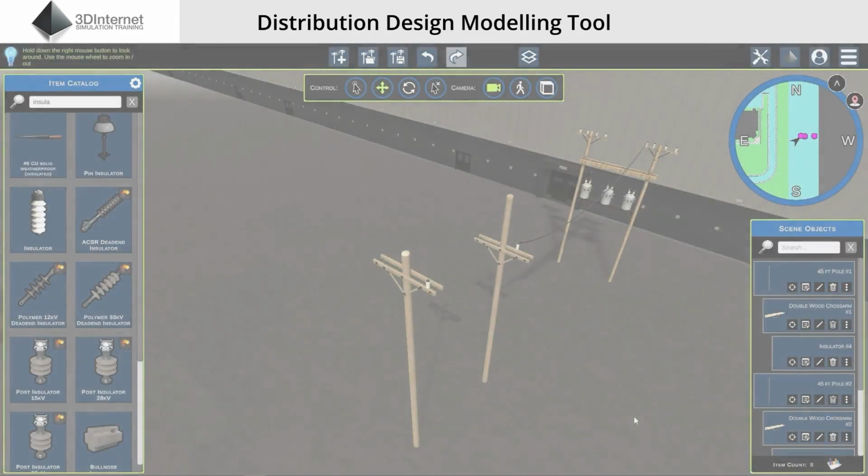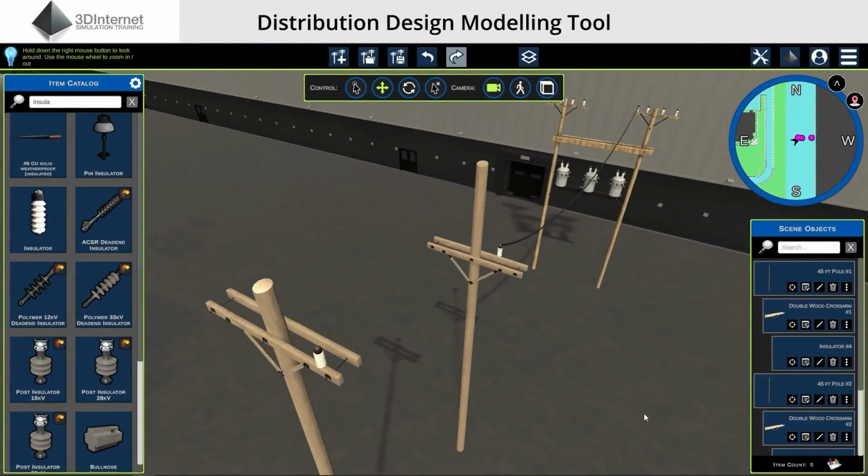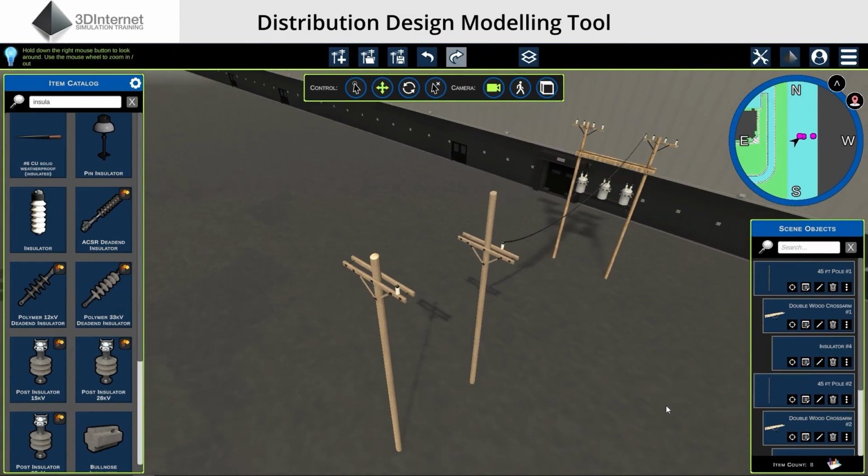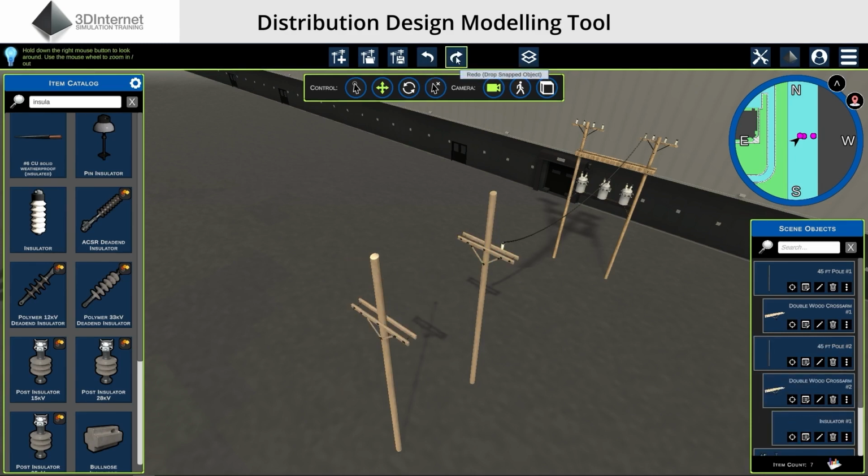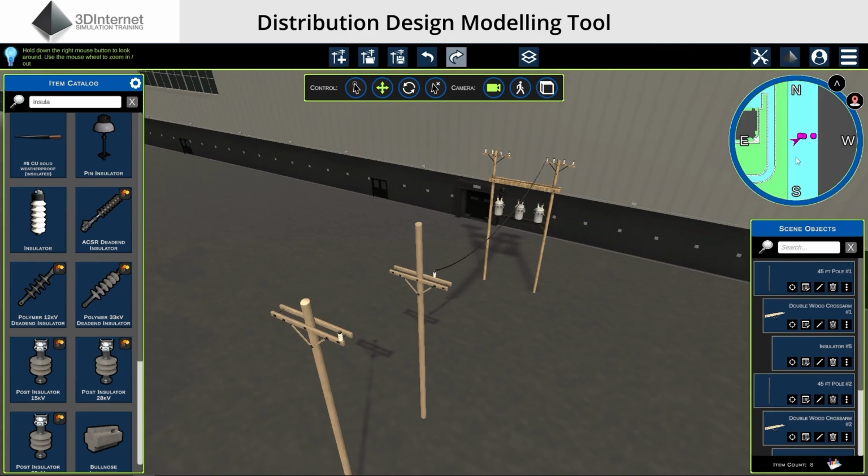Time machine. Sometimes when developing a design, it may be necessary to revert back to a previous iteration of the design and then proceed to modify and make refinements from that version. The time machine allows for this kind of functionality and is more robust than the undo and redo system that the modeling tool offers. Under the Options menu, click the Time Machine menu item.